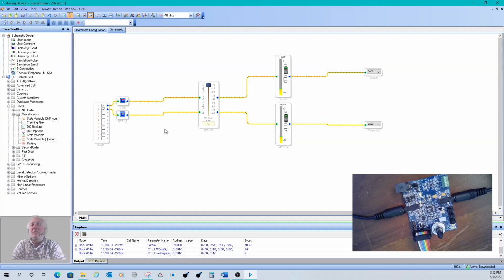Now, for testing purposes, because you don't always have a good audio source, if I hit play and I got nothing, I do have the meters. That helps. I can see, well, yeah, there's something coming in. But what I also like to be able to do is generate a signal from inside the DSP. So let's do that, because we can then test from inside the DSP out. Especially handy for serial digital because you can check the level with a known level. So anyhow, let's do that. If we go to the sources, we have many different kinds of sources we can add.